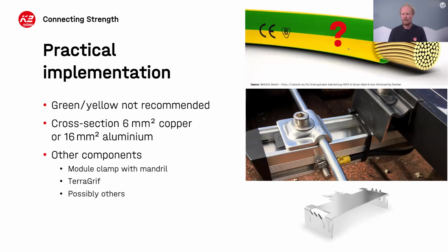On the flip side, if you have a functional equipotential bonding, this must not have a green and yellow cable. So to be safe, you could always use a green and yellow cable, and this would meet the requirements of one and the optional extra of the other.